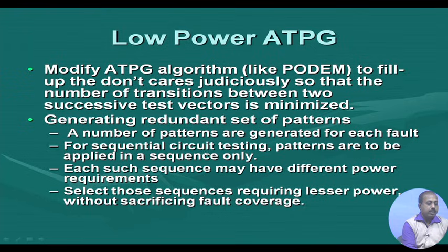For sequential circuit testing, patterns are to be applied in a sequence only. Though we did not discuss sequential ATPG in general, what happens in that case is the first pattern or a set of patterns will take the circuit to a particular state, and then the final pattern will actually excite the fault.